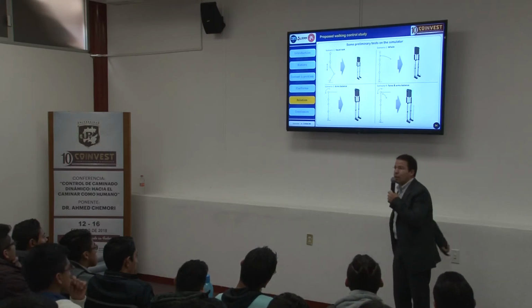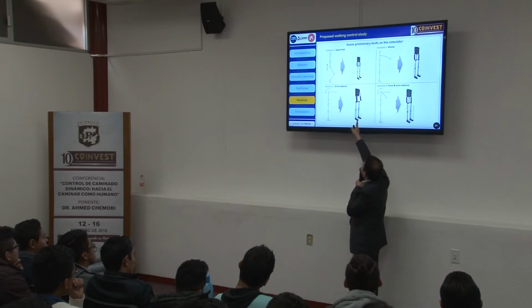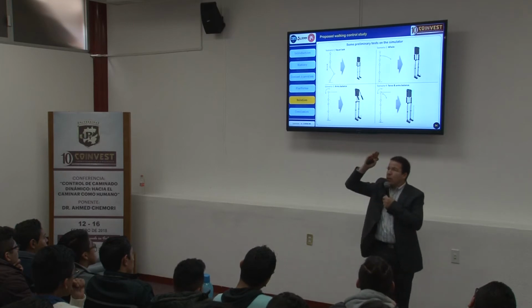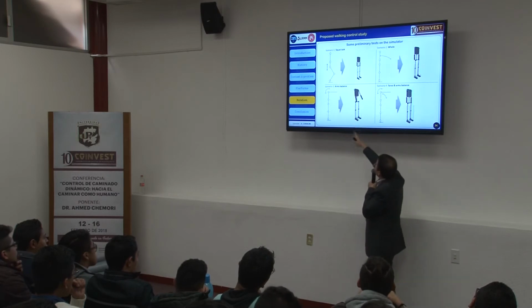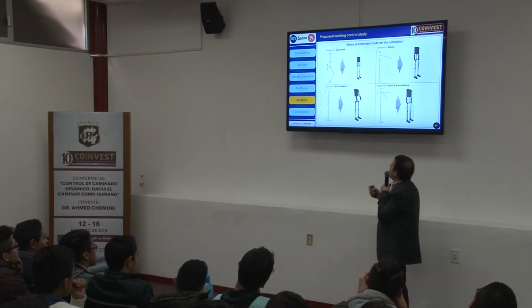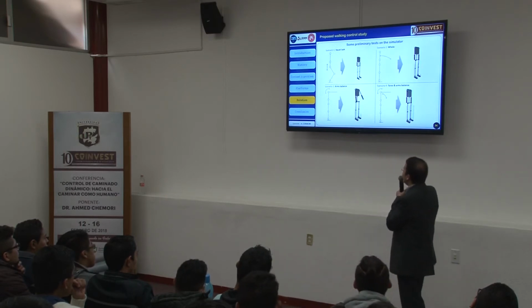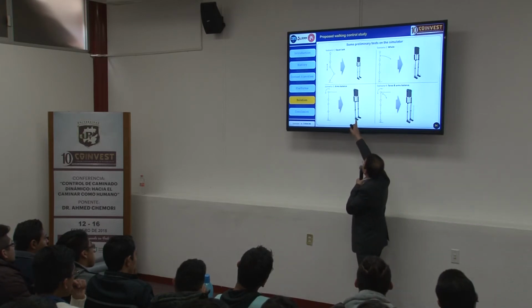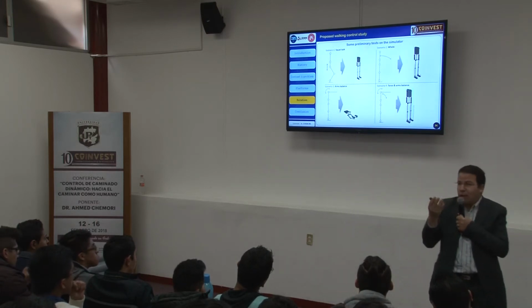Here we try to do a balance of the arm. So we do a swing of the arm, and we can see also how the contact forces change here, and the ZMP, how it moves. And here inside, you have 2 points, blue and red, in the middle. One is the center of mass, and the other one is the ZMP. And look, it's balancing, and it's realistic since it shows what happens on the robot. Even when the robot falls down, we can see this on the video. With the change in forces, the ZMP is outside, and it's falling down. So this is a realistic simulator that will be used to validate our controllers.